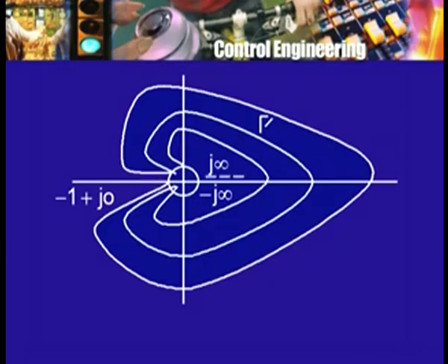Although in practice, if I write here j infinity, I do not really mean that I apply a signal of infinite frequency and make any measurement. That is all nonsense. There is no signal of infinite frequency that I can ever apply, but I can apply a signal of whatever high frequency is under my choice, whatever signal generator which will provide some power to drive the motor. In the case of the motor, it may not really be of the order of megahertz or even kilohertz, it may be of the order of a few hundred hertz. Still, that may be adequate, because the frequency response will be such that it is virtually very small. So, this is what we mean here.